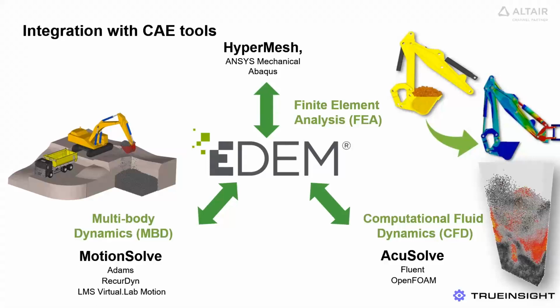For example, bulk material loads from EDEM can be coupled with Altair HyperMesh for use as input to an FEA analysis. This is useful for helping engineers define loads accurately in an FEA analysis when those loads are a result of the interaction with bulk materials.